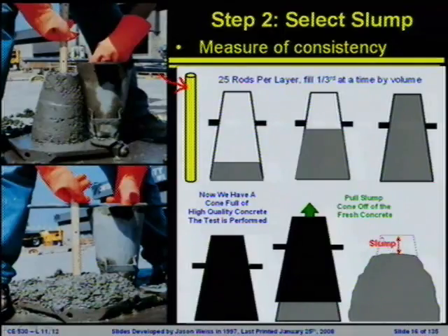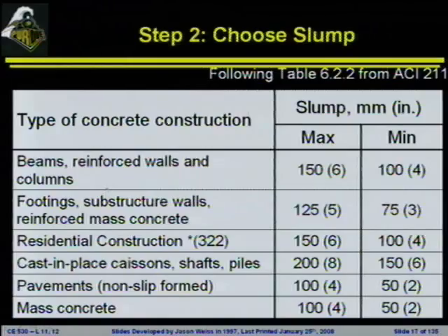The amount that the concrete sinks or slumps is the number that you will hear people referring to as the slump number. So if someone tells you it's a slump of 4, at least in this region of the world, that means it is 4 inches. You can see at the top here a concrete with a low slump, about 1.5 or 2 inches. At the bottom is a high slump concrete, about 9 or 10 inches, where we're really getting out of the reasonable range of what that slump should actually be measuring for this particular test.